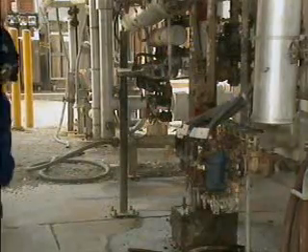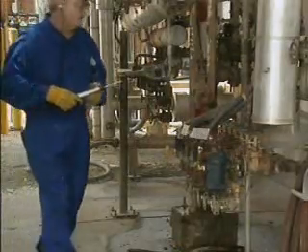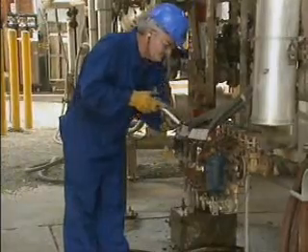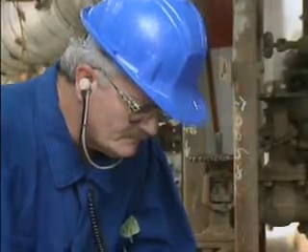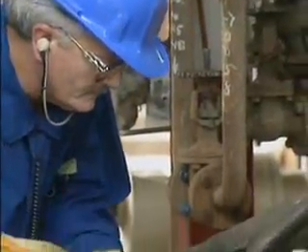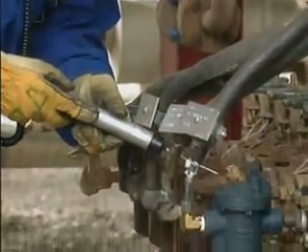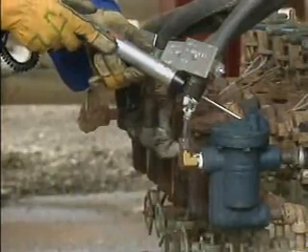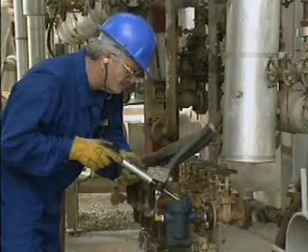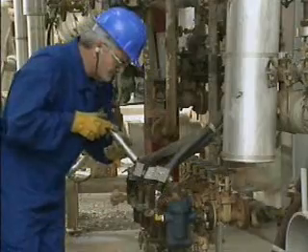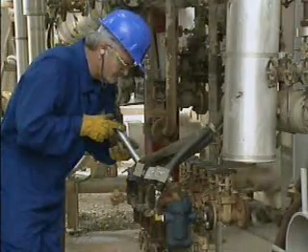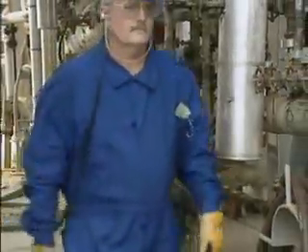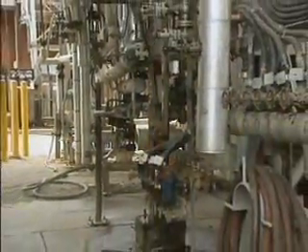Even with the help of a listening device, filtering out noise is especially difficult if several traps in a manifold discharge to a single header, because sound can travel from trap to trap through the piping, and a good trap could be telegraphing or conveying the signal of a malfunctioning one. So if you detect the sound of a malfunctioning trap while you're performing a sound inspection at a trap manifold, keep in mind that the failed trap is usually the one that's producing the loudest signal.